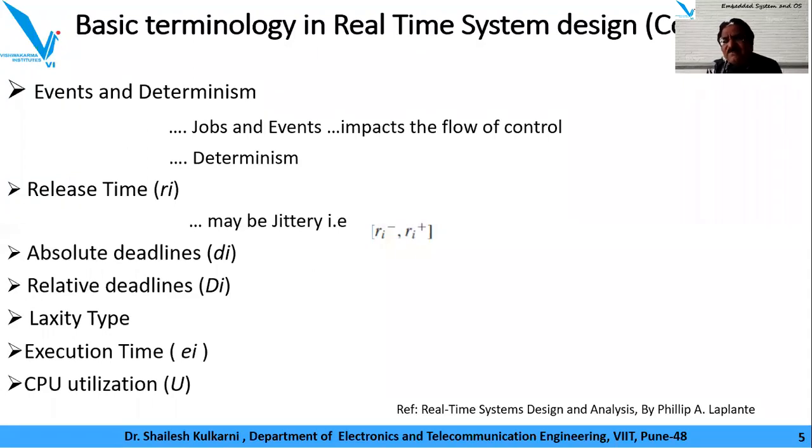If that is known a priori, then I can refer to my system as a deterministic system or a highly predictable system. If you happen to know the term FSM, finite state machines, we understand that the output state of that machine depends either on the input condition and the state at that moment, or on the input condition, the previous input condition and the state at that moment. Based on that, we even have the categorization of Mealy and Moore state machines, isn't it?